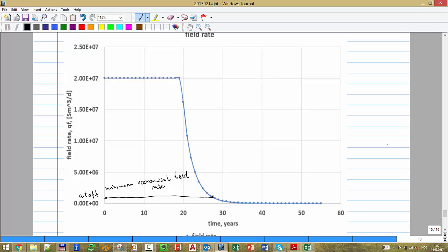As I told you, it's a shame we cannot use the reservoir simulator. It's really very interesting. You need to gather and quality control all the input. But this is, in a simplified way, how the simulator is working: applying the pressure, calculating a potential, and then comparing the potential with what you provided. If you see here, how are we calculating the GP? We're saying that the rate is constant for that particular year.